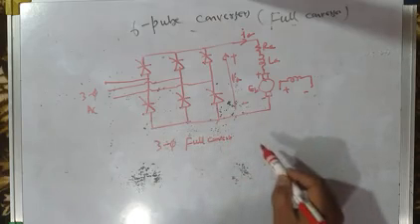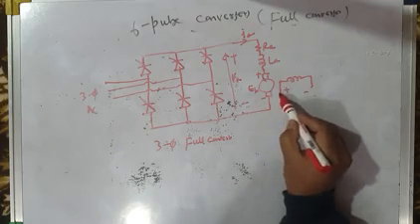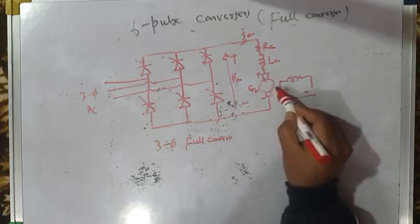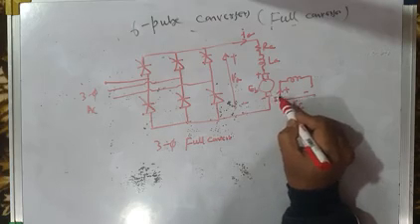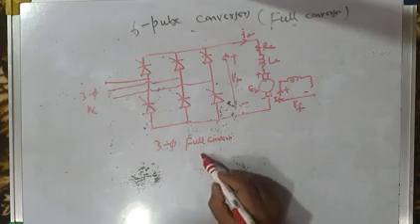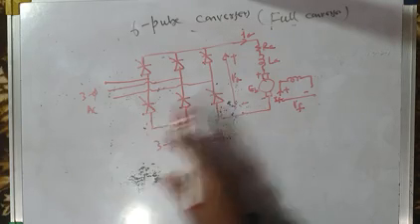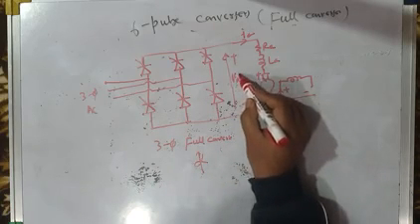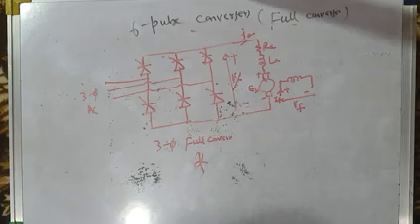So again, you may use a three-phase bridge rectifier, which will convert AC into DC and produce DC field voltage VF, resulting in the flow of field current IF, which is equal to the rated field current. And by firing angle control, alpha control, you can achieve a wide range of torque control, speed control, because this VA changes when alpha changes.